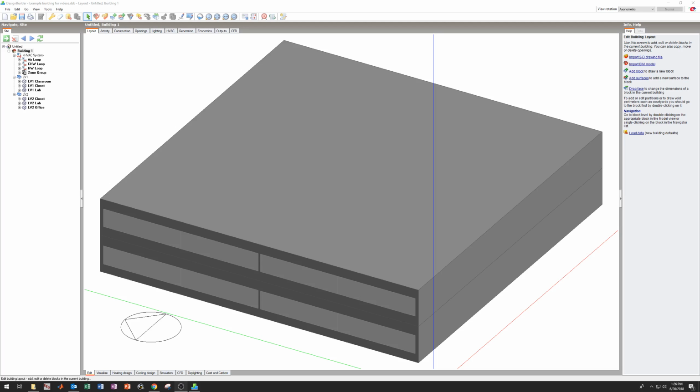The problem with this is that EnergyPlus, which is the engine that DesignBuilder uses, does not allow two different types of radiative sources within one surface. This is because it treats the ceiling of one floor as the floor of the floor above it. So you couldn't have, like, a chilled pipe, a bunch of insulation, then a hot pipe in the floor.